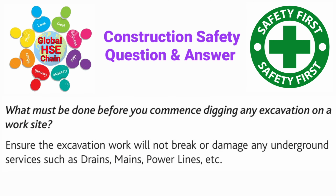Question is, what must be done before you commence digging any excavation on a work site? The answer is, ensure the excavation work will not break or damage any underground services such as drains, mains, power lines, etc.